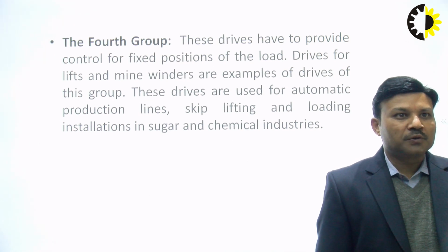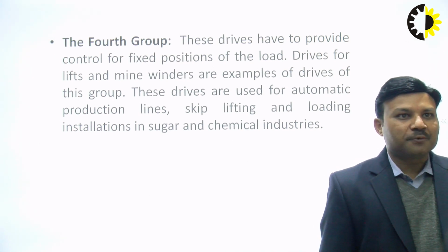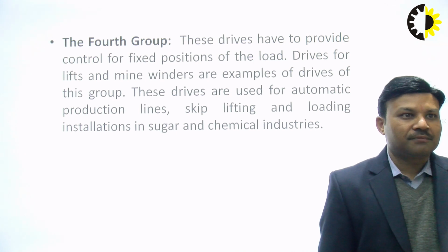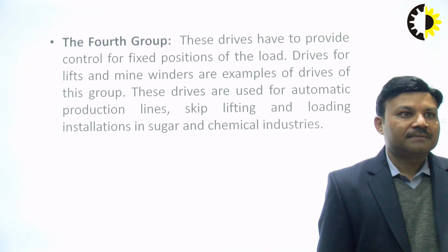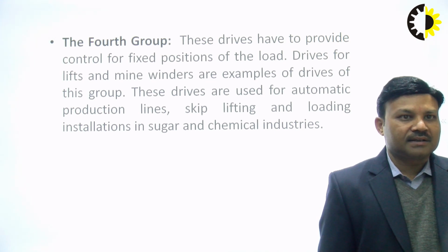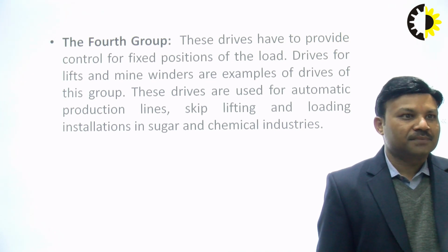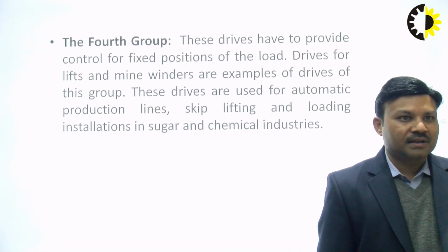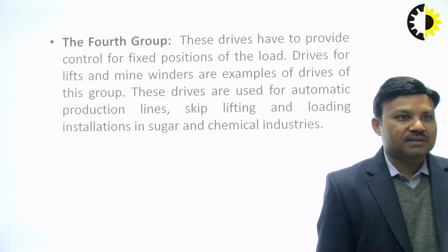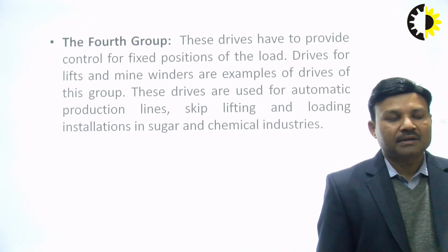In the fourth group, these drives have to provide control for a fixed position of load. Drives for lifts and mine winders are examples of drives of this group. These drives are used for automatic production lines, skip lifting and loading installations in sugar and chemical industries.